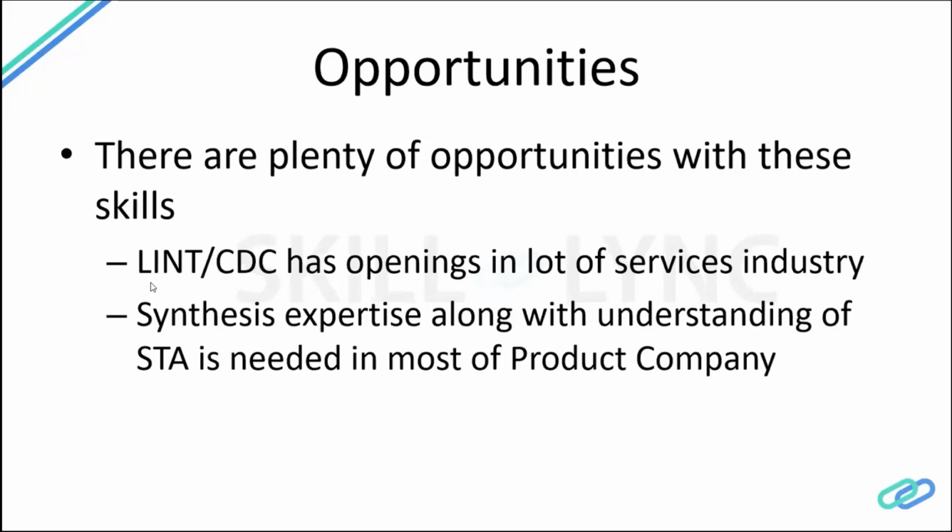They'll be changing some parameters, some clocks. From our end we have to run the lint tools, CDC tools. We have to generate the reports and see if all the reports are correct or not. If we need to fix anything, we don't fix as is, we check with the seniors whether that is the right thing or not. Review and synthesize.